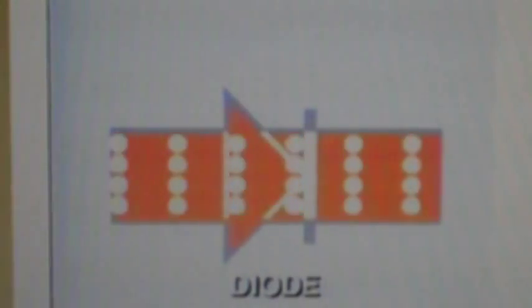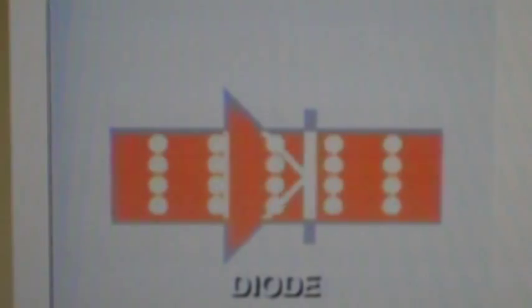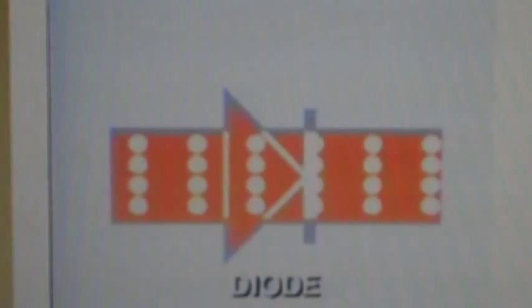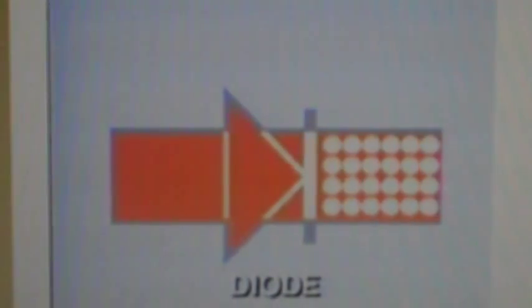A diode is a common motorcycle application of a semiconductor. Think of it as kind of an electronic one-way valve. It will conduct electricity in one direction, but not the other. You'll find other semiconductors in motorcycle electrical systems. For example, transistors act as solid-state relays, while thyristors are solid-state switches. Electronic control units found in many electrical systems are made up of hundreds of these semiconductors.